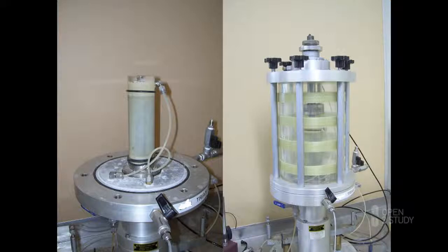On the left of this photo, you can see the base of your triaxial cell, which includes a pedestal on which the specimen sits. The specimen also has a loading cap on top of it. On the right of the photo, you can see that a bell has been placed on top of the base of the triaxial cell. That is used so that we can fill the bell with water. The water will be pressurized, and that pressure of water will provide the confinement to the specimen we were talking about earlier in this topic.